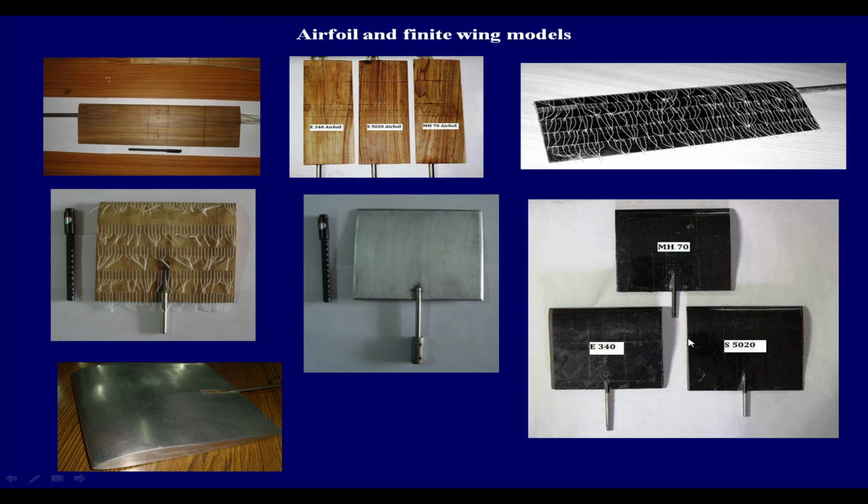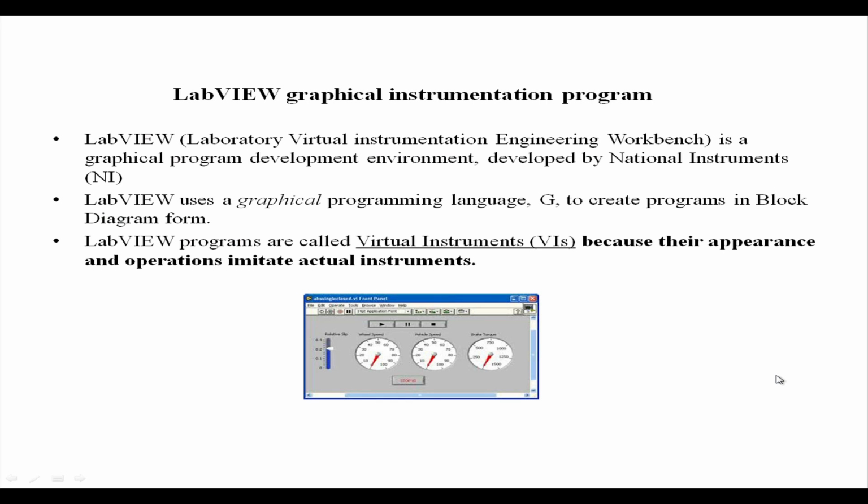So, these are sections which are typically more popular in the smaller configurations, where the operating speeds are lower, the characteristic dimensions are smaller, and consequently the Reynolds numbers are of a much lower order. And that is why you are talking about a completely different regime where you have to operate, and therefore, the classical airfoil sections may not be doing the best, and that is how these sections have emerged. So, we have a couple of them over here.